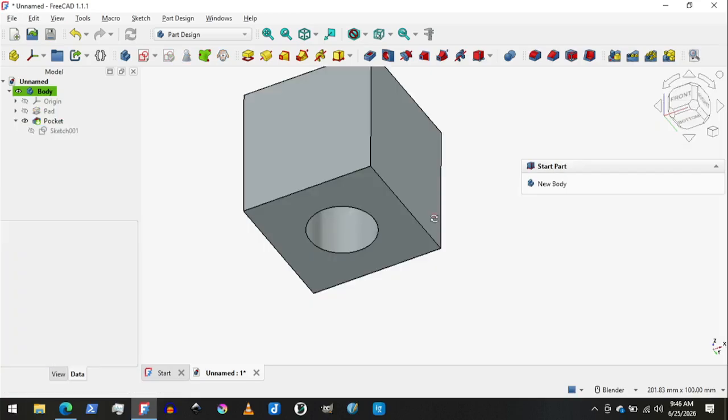So I've done these, and I'm just going to make diagonal lines from corner to corner. I'll switch back to regular lines, which will actually be there, and I'm going to draw a circle. I'm not really worried right now about making that circle the right size. I don't really care where it goes, and you can see because of how I drew it, if I try to move my mouse, it's stuck to this line. I don't want that. I want it to be attached to the line, not the edge. So for the constraint that I don't want, I can go down here and just delete it. Now when I go to move this, I can move it freely.